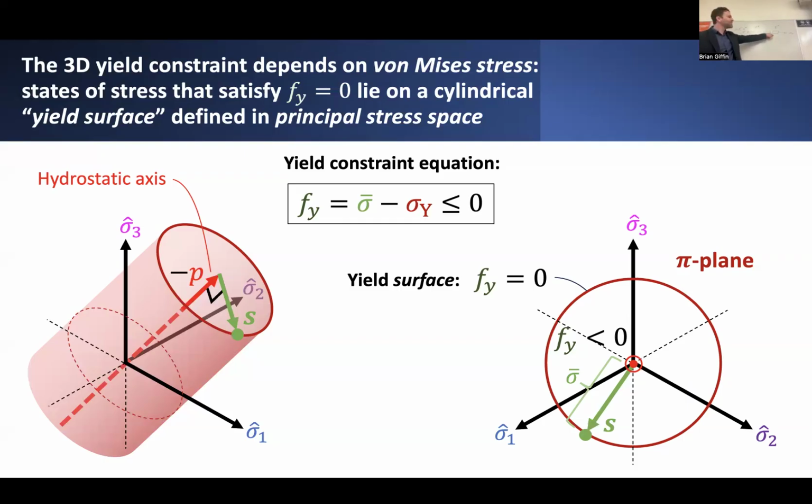And at least in this one-dimensional case, it basically means that this plastic strain will start to increase if I start to increase the amount of applied stress on this whole assembly. And at that point, once I start to have yielding, the plastic strain will start to increase if I'm putting this thing in tension, or if I'm putting it into compression, the plastic strain will start to decrease.